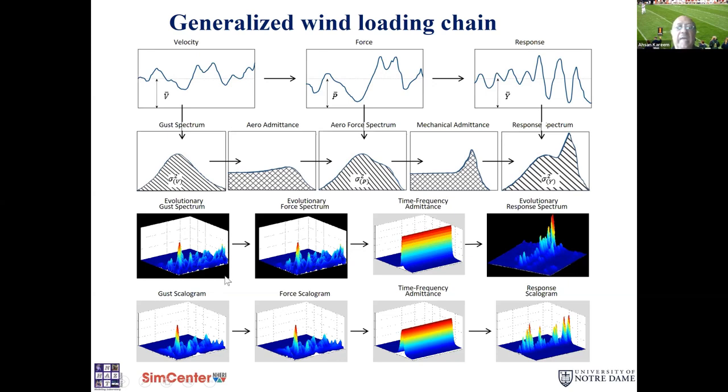in non-stationary wind. It would be different for downbursts, different for tornadoes, different for hurricanes. So I think that's where I suggest that we should look more into a design evolutionary gust spectrum, just like design spectra for earthquakes. We should look into a similar approach, because otherwise every storm is different. We cannot take care of every one, but if we standardize what we are going to design for, I think we will have expressions available for all these as well.